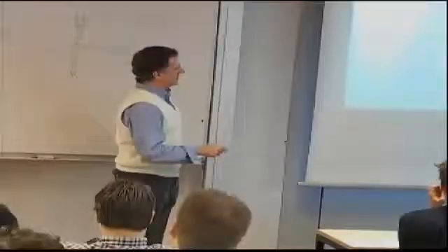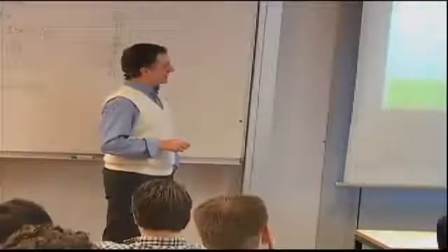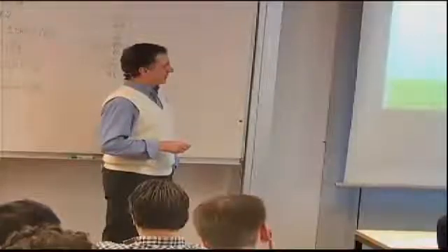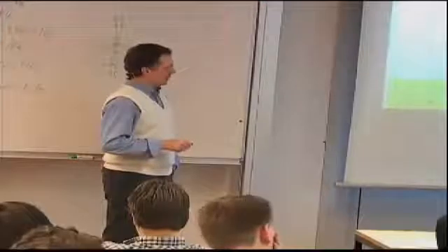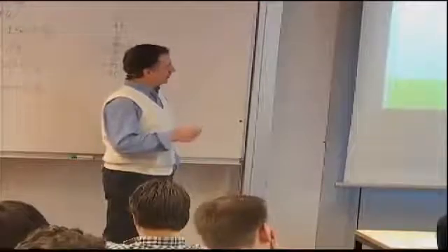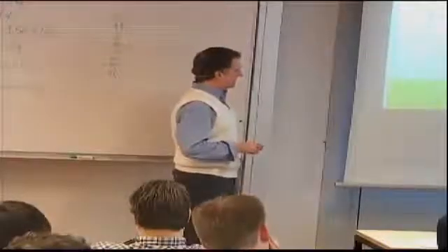That is the same equation here. If my B matrix is 0, then I will only have the W dependence. But in a buckling kind of problem, I pick up terms which involve my NX, NY, and NXY with derivatives of W, plus my usual out-of-plane loading. PZ is the load per unit area, and then Px and Py loads again per unit area in the X and Y direction.